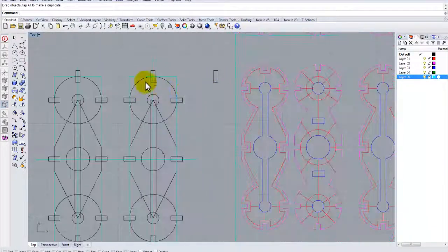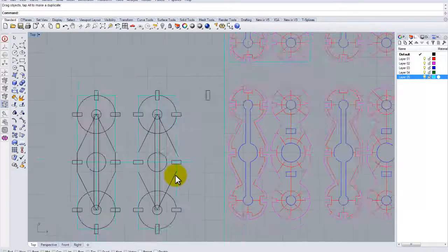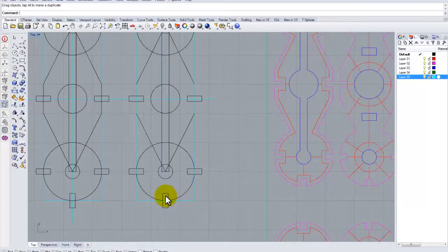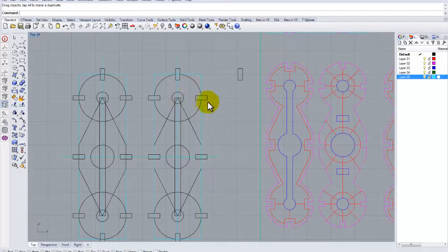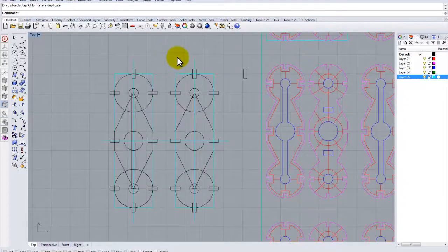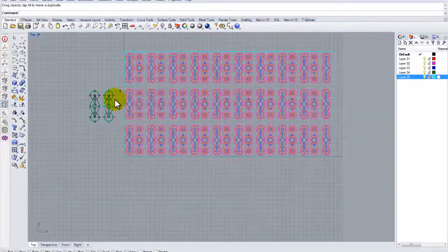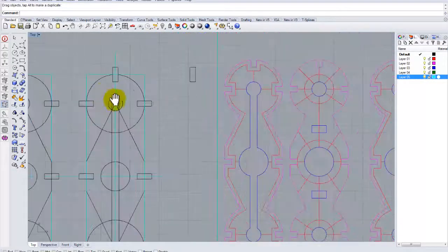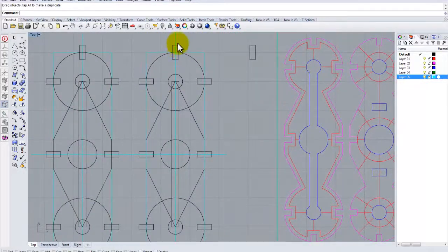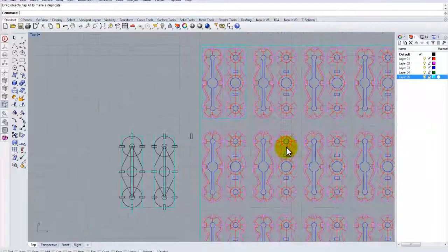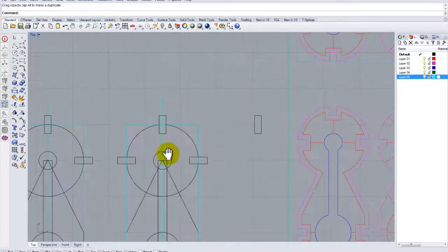Also, these squares right here represent our material thickness notches. It's very important that you caliper and measure your material before you cut out these notches. And the nice thing about the way that we're going to do this, you're going to make a unit form that you're going to repeat throughout the design. So if you have to go back and fix and change things, you'll do that at the unit form level. So you're not going to have to go back and change every one. You have to just change it in the unit form.